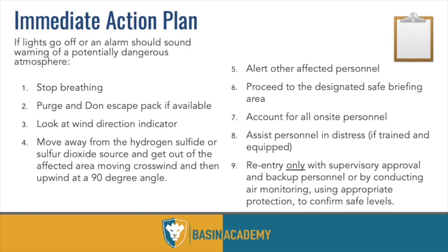Make sure that we understand wind direction. My advice to you is to always be aware of the wind direction on site, wherever you are. Like, I'm upwind, I'm crosswind, I'm downwind of the wellhead, of the treater, of the tanks, wherever you are all the time. And then you want to move crosswind and then upwind, as we already talked about.